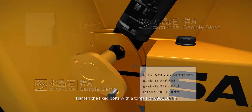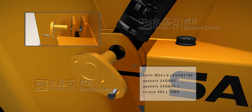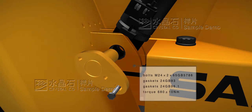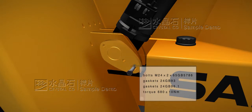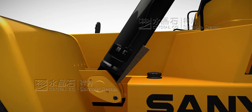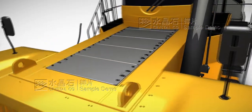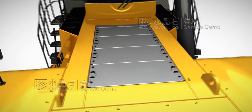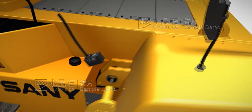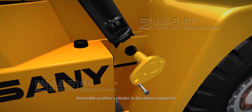Tighten the fixed bolts with a torque of 680 plus or minus 10 Nm. Wedge pads between the cylinder and frame body to support the cylinder. Assemble another cylinder in the above sequence.